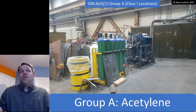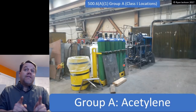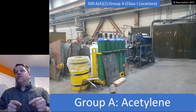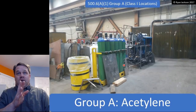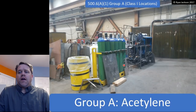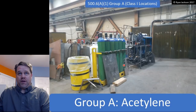No. So the fact that you're welding in an area is evidence that you're not in a hazardous location. If you're in a hazardous location and you're welding, you blow up, you die, right? So when I say acetylene, that doesn't necessarily mean that you have acetylene. That means you have acetylene in the room in ignitable mixtures.